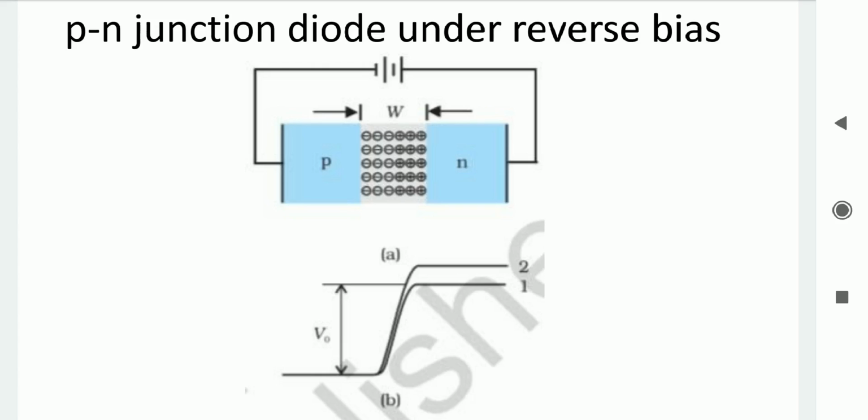After that limit, if we increase the supply voltage, it will cause a large change in the current. So the reverse current is now not in control or limited by the external supply, and the PN junction can be destroyed, which will completely destroy the diode, which we cannot use further, and overheating starts to produce.